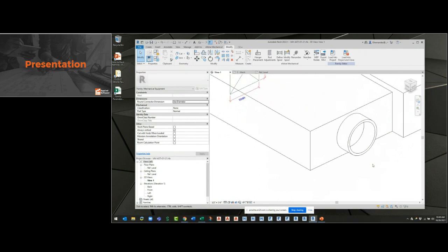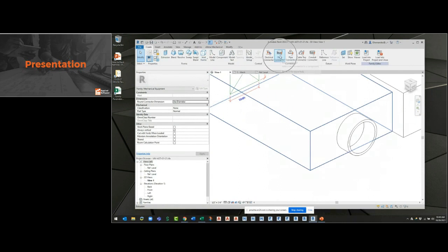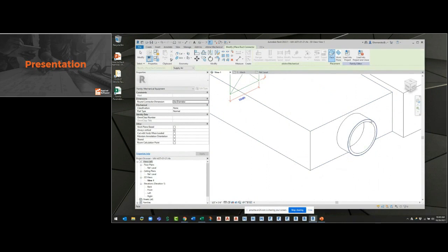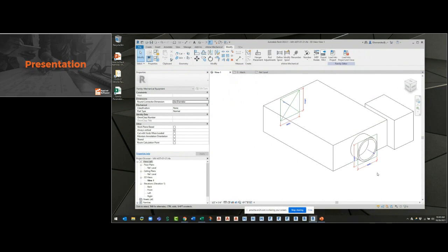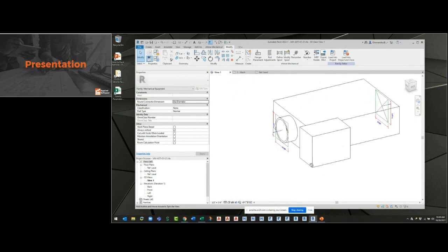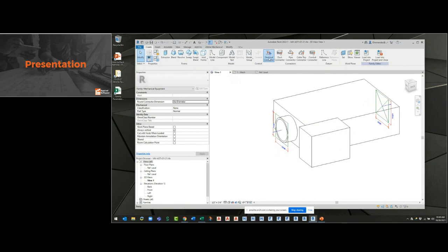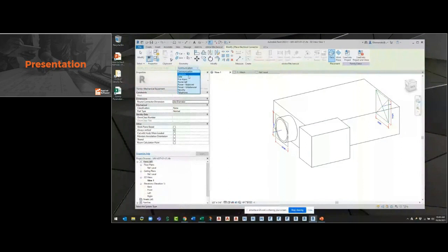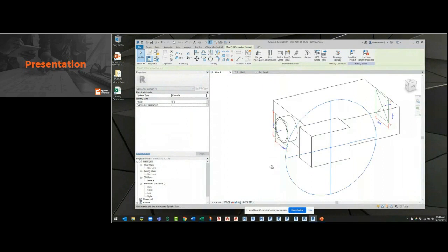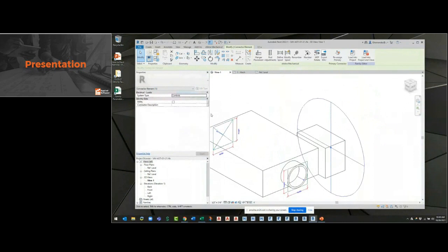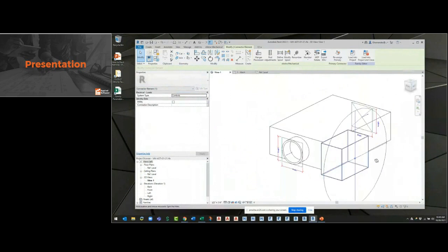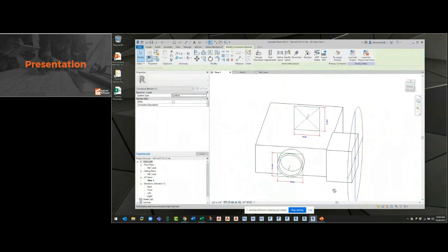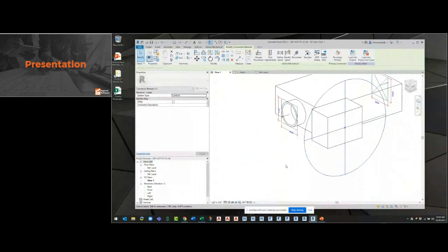On this side, same thing. I can go to create here, pick on a duct connector. I'm going to hover over the surface of the cylinder there and place in my duct connector, okay? Now, the electrical connector, we're just going to throw in just for giggles. Go here and do electrical connector. I'm going to say that this is a control, and I'm going to put this on the surface here. Now, the reason why I do this, because you might see this in other families, is just for the electrical side of things in Revit, but with this connector, you can't control the scale or the way it looks. It is what it is, so you need to see what it looks like, okay?